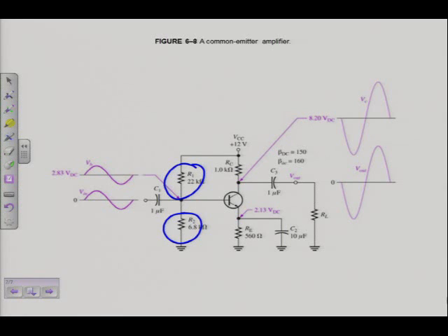We've established why this is a common emitter amplifier. Did we discuss that already? Can you still distinguish between the different types of configurations? Have we discussed that? We haven't. Let's just make sure again. Remember, we've mentioned the different configurations in the previous section. How do I distinguish between the different configurations? I go and have a look at my amplifier: on which terminal of the transistor is the input applied, on which terminal is the output applied. The remaining terminal makes it the configuration.